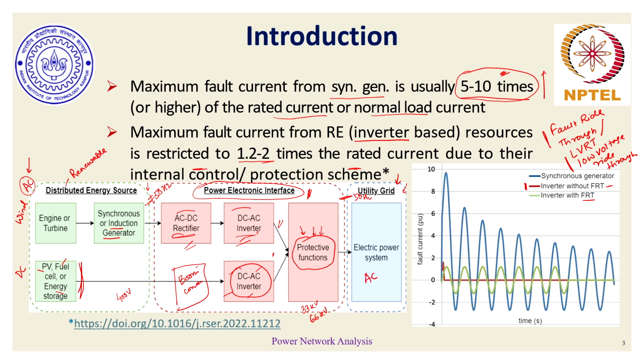So basically, what is FRT or LVRT? Given the limited time that we have, FRT or LVRT refers to the mechanism of a generator still being connected to the power network while it is experiencing a fault. This ride-through capability is important to still support the system without going into an unstable or blackout condition.